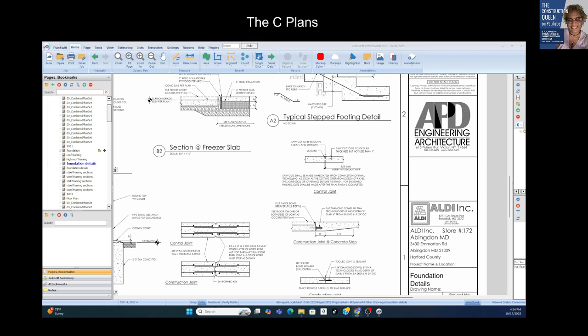And then we have spread footings, which are like the ones we saw on the plan, where it's a perimeter kind of thing, right? It spreads out and doesn't cover the full area, and this is for residential more than commercial, where we don't have a mat like a slab on grade where the building just sits on top. Well, we spread them out to a distance to where the perimeter of the building is sitting on it nicely.